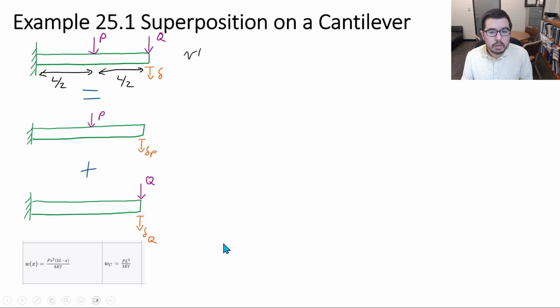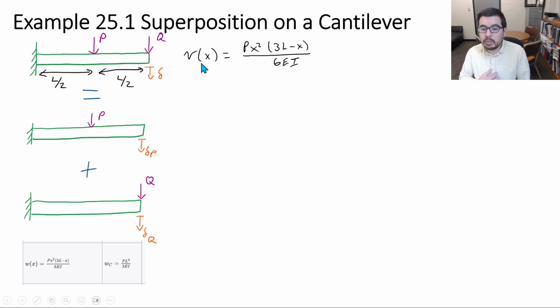All right, so coming over to writing the equation here in a bigger view and in our terminology with V, the convention is maybe a little different, because often we say it's negative when we've been integrating, since we find V in the vertical direction, positive upward. But here we're going to use a little bit of our experience and understand that this V, the displacement, is going to be downward with these loads. So this is just writing that expression for displacement.